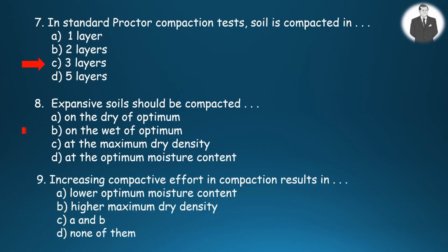And the final question, increasing compactive effort in compaction brings about what? No, not only lower optimum moisture content, but also higher maximum dry density. So the answer is C.